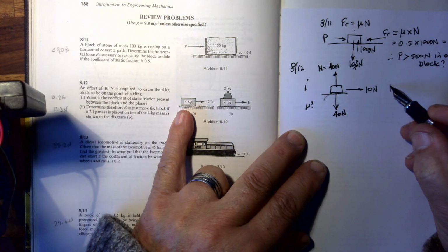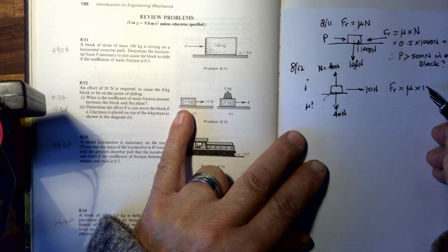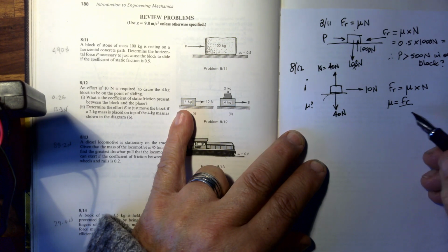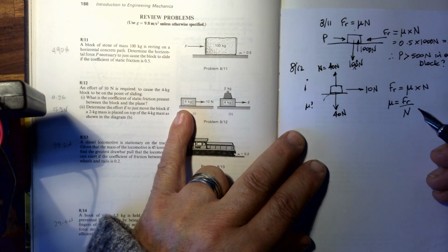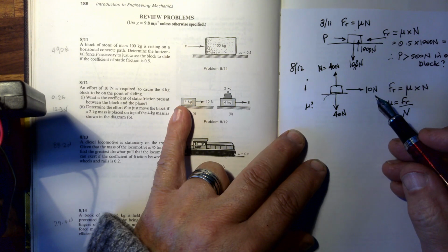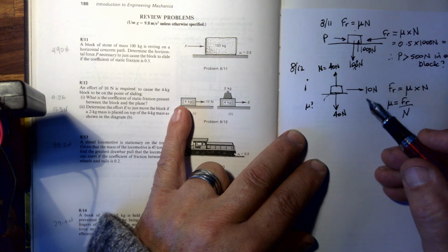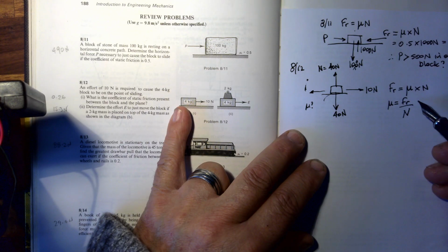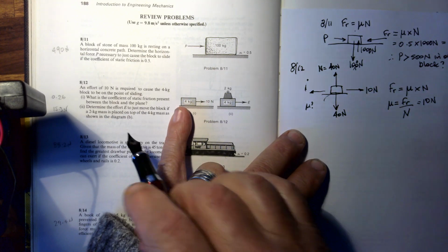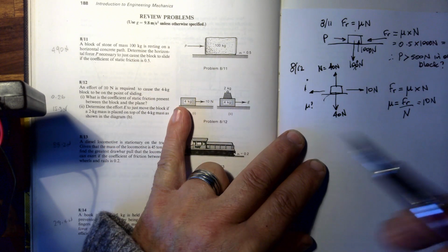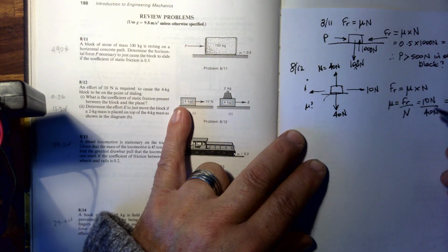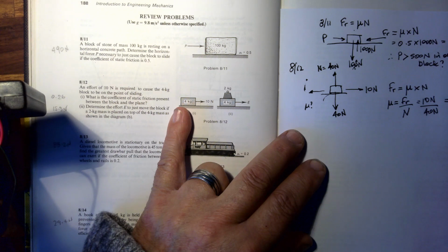Okay, well, let's use our formula again. The frictional force is equal to mu times N. Now in this case, we want to know what mu is. So mu is going to equal the frictional resistance force divided by N. Now we know that the force necessary to make it move has to be 10 newtons, which means that the frictional resistance force can only be 10 newtons or less. So we're going to assume it's on the point of moving, therefore the frictional resistance force would have to be 10 newtons, because it tells us it's going to start moving with 10 newtons of force. We know that the normal reaction force is going to be 40 newtons. Therefore the coefficient of friction has to be 10 on 40, which is 1 on 4, which is 0.25. There's no units because it's just a coefficient. So there's the answer there.